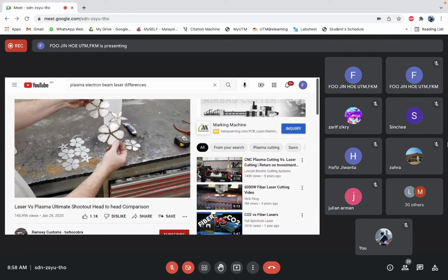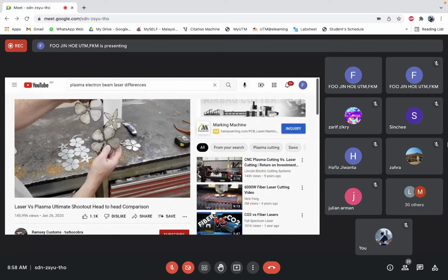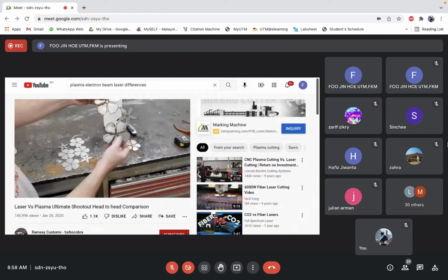lots of dross. Now I've seen guys take these, and by the time you get them twisted and bent up, that dross will come off while you're doing that. Depends on how you decide to finish these. But you may be working on something else where you're not bending it. And even though there's not a lot of dross in some areas, the areas that do have dross, it's on there pretty hard.